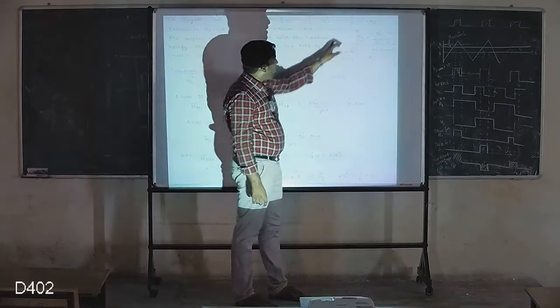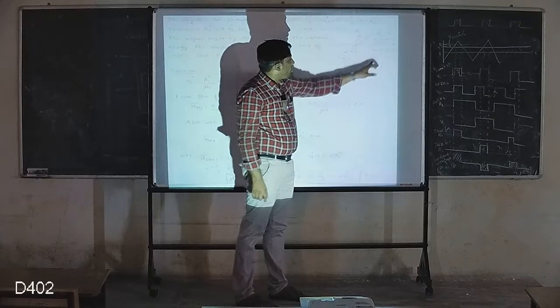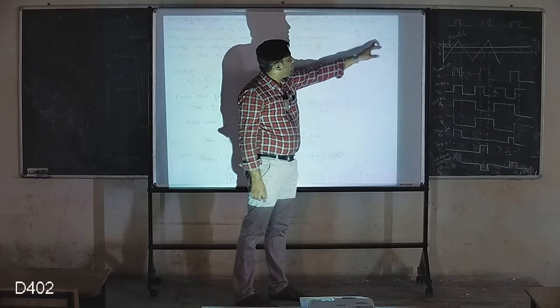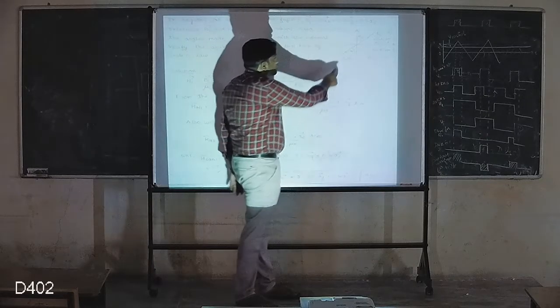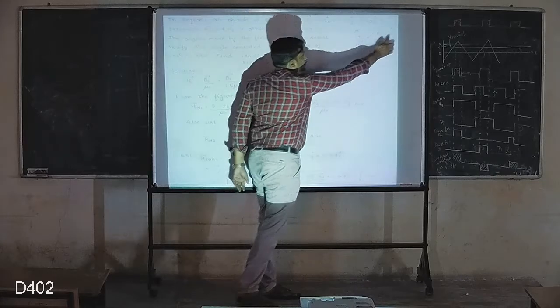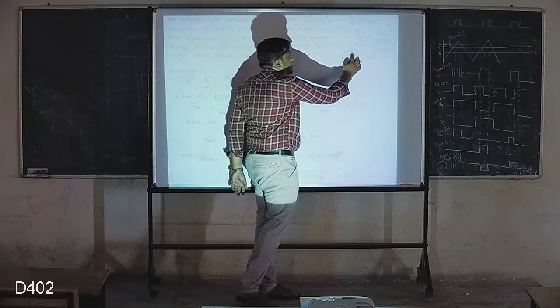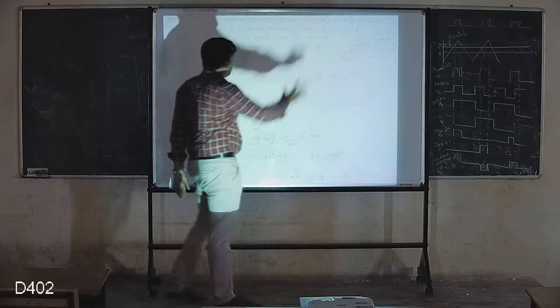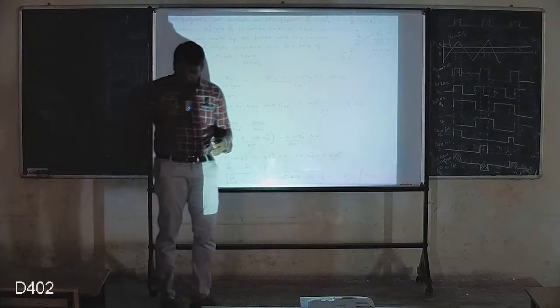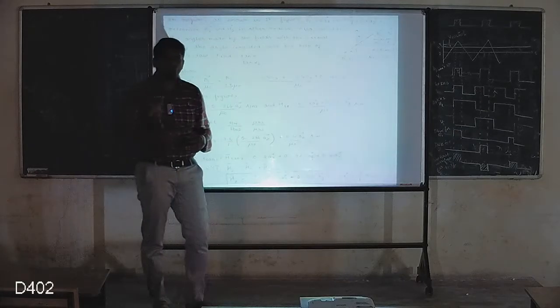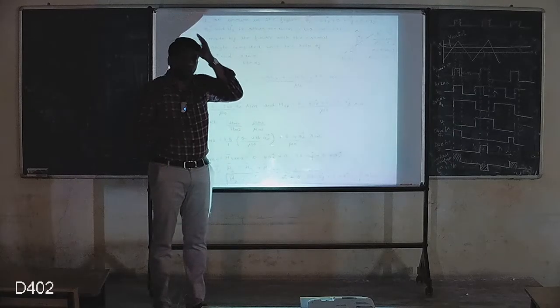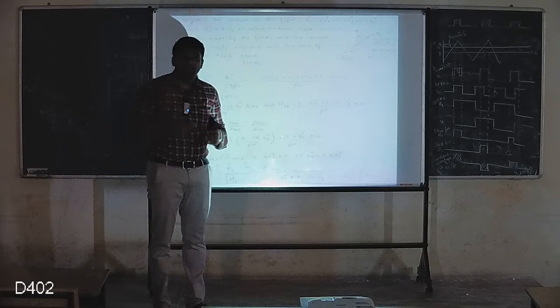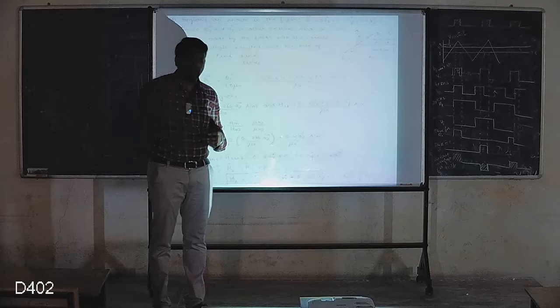Here the diagram is given. Here it is region 1, region 2. In region 1, the medium is 1.5. In region 2, the medium is 1, air medium. So B1, H1, B2, H2, and the angles made are alpha 1, alpha 2. This is the given problem. During our derivation of boundary conditions, we have 4 important formulas, out of which 2 are HT1 is equal to HT2 and BN1 is equal to BN2. With the help of these 2 formulas, I can claim the other 2 formulas.